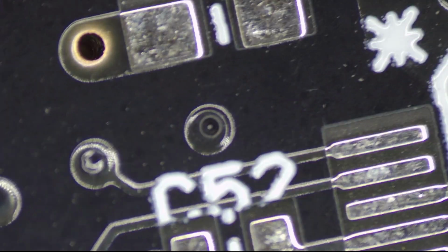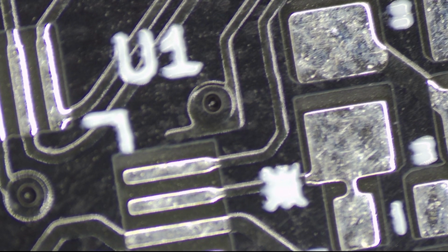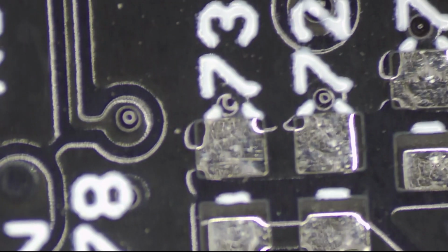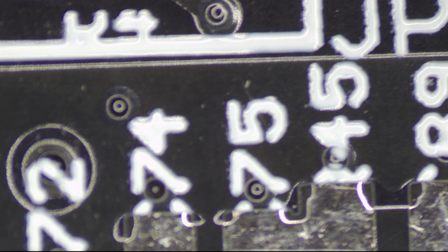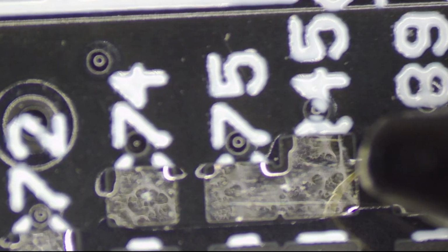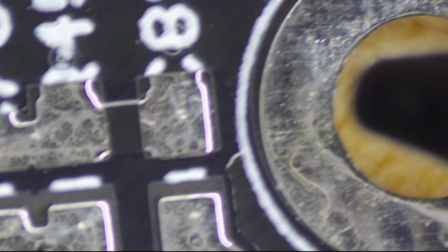Sometimes on this other board here, let's try to find a few. There's some where you can kind of see, hopefully, that the solder mask is actually giving you a surface. And if I find a via with some text over it, some of these aren't good because I've cut them back. See, these overlap. Okay, there we go. So there's a 4 here. Where's my pointer? Right, this 4 here is overlapping with the via. So it's cut off because of the pad.